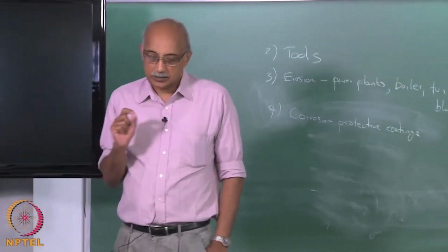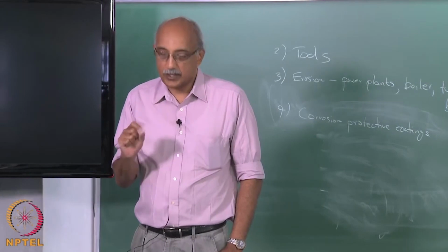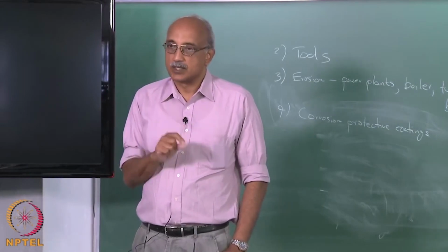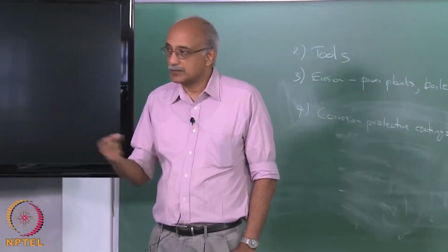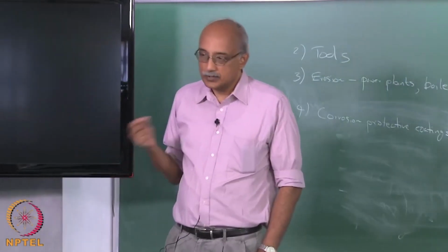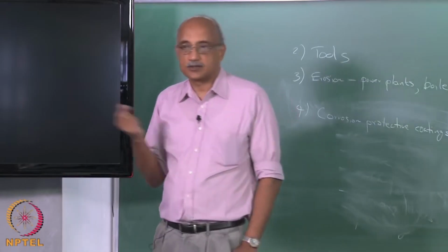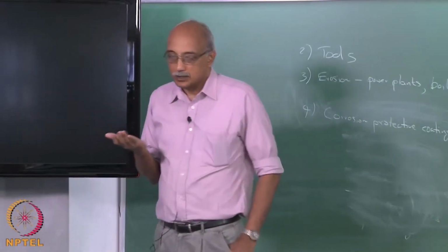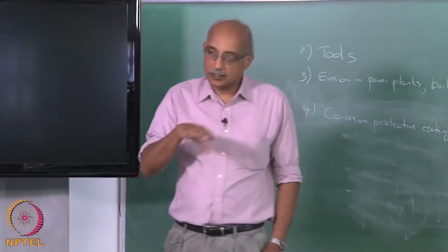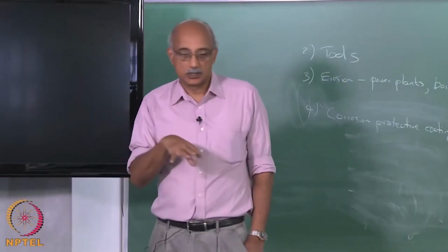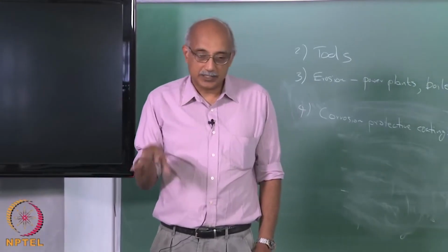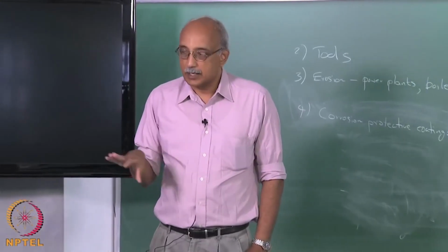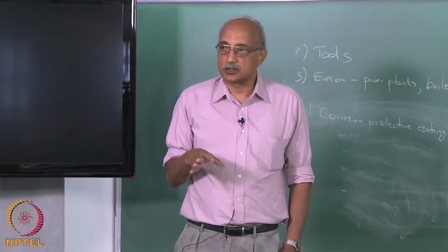The primary reason is that stainless steel manufacturing introduces impurities, and it is these impurities that really initiate the corrosion and then it quickly spreads. So, even though you may have stainless steel as your substrate material, you have to provide additional protection to it, and especially if you start using the less expensive steel alloys, this becomes even more important.